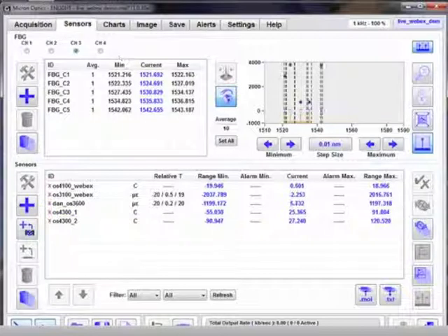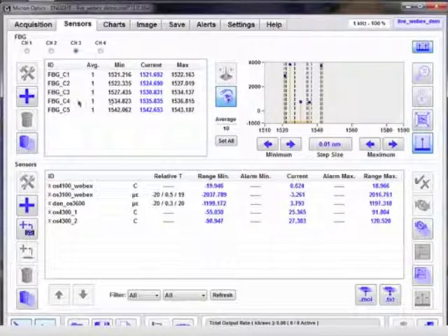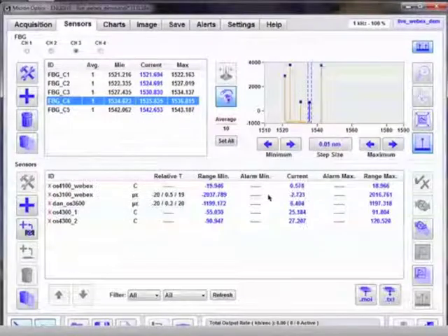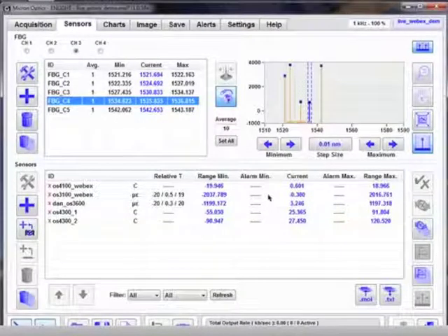So if you had 3 strain gauges being temperature compensated by a single OS4100, and you had zeroed them, say, 3 months ago, and then you needed to add a couple more strain gauges to your structure after seeing what was happening with the structure over the monitoring of the system, you'd come back, install those new strain gauges, come into Nlight, and reference that FBG in reference mode, but it would show an offset. So you would have to re-zero the FBG in previous versions in order to reference the new strain gauge.